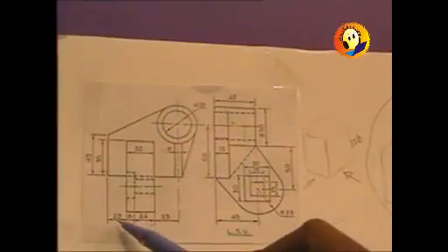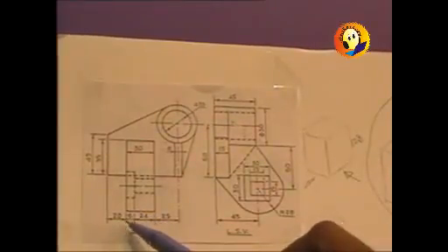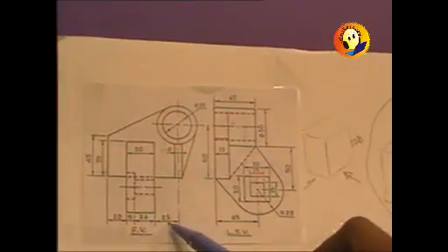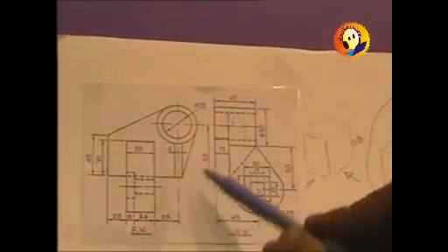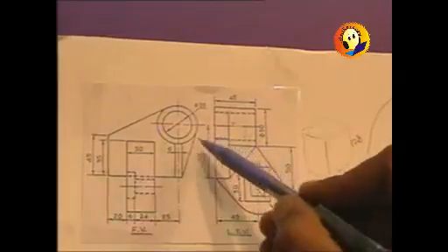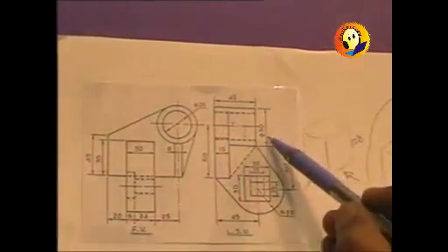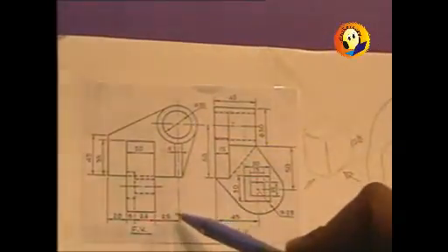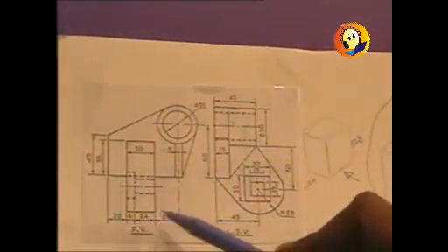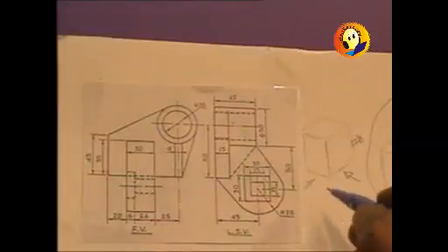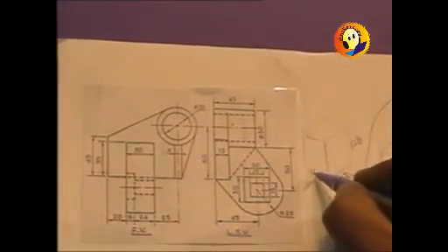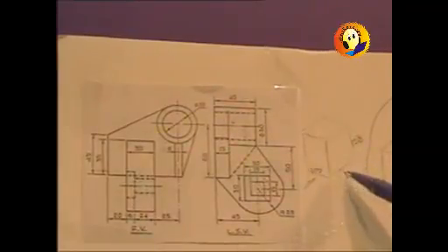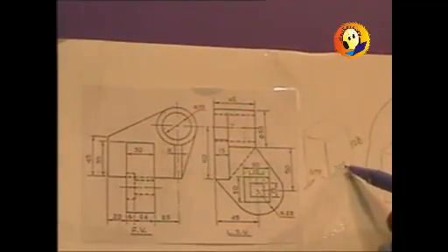So let us measure the total width of the front view, which is 20 plus 6, 26, plus 24, 50, plus 25, that is 75, and plus this radius which is given to us here as 50. So that means this radius is 25. So it is going to be 50 plus 50, in all 100 millimeters. So this is 100. And then the side view, this is front view direction, this should be 100.